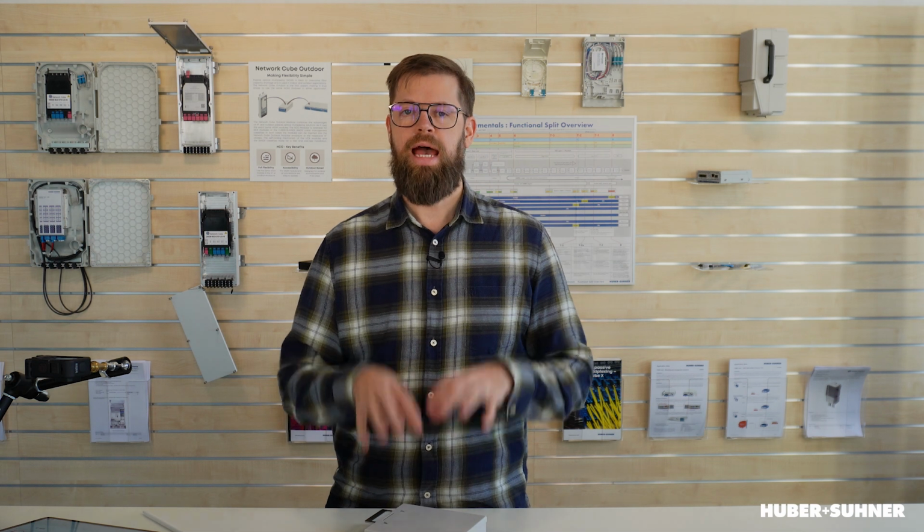However, when we're talking about a data rate of 100 gig or higher, then another negative effect becomes stronger, and that is the negative interference of the reflected light with the original signal. Now, the optical return loss specified for a multiplexer describes how much return loss the multiplexer itself introduces. And since the return loss is a negative value, of course you're looking for a higher number to have a better return loss.